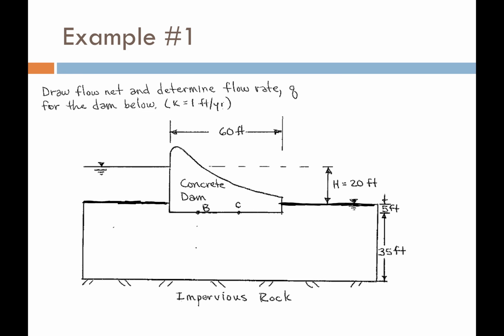I also am going to want to demonstrate and establish the habit, right off the bat, of establishing a datum. Okay, so I'm going to call my datum this impervious rock that's down here on the base. That's going to be the datum from which I measure total heads and elevation heads for any point in my flow net.